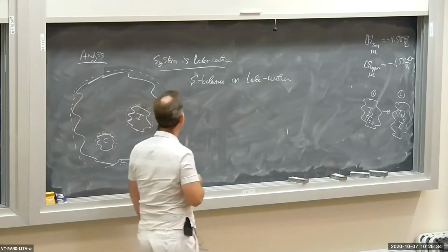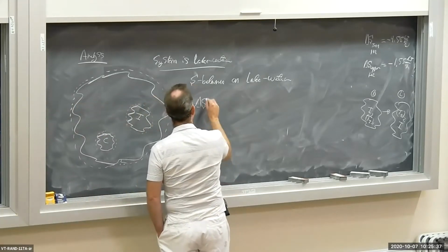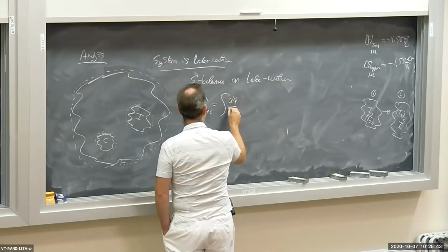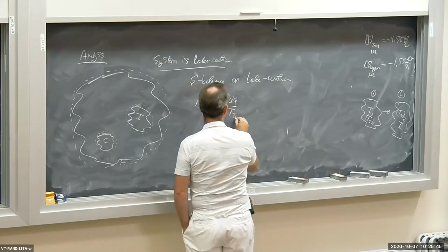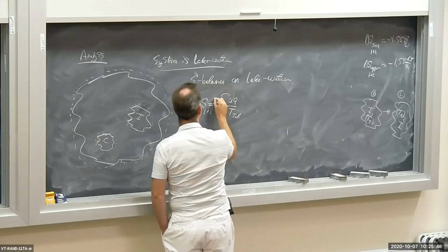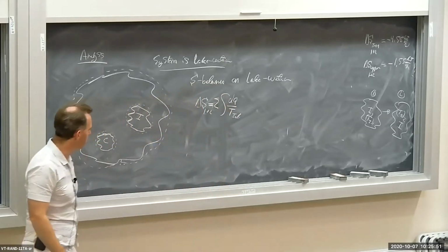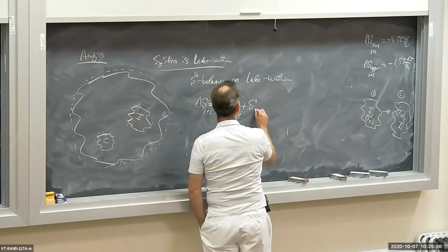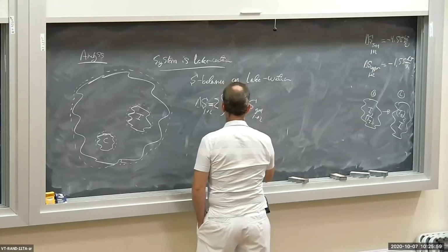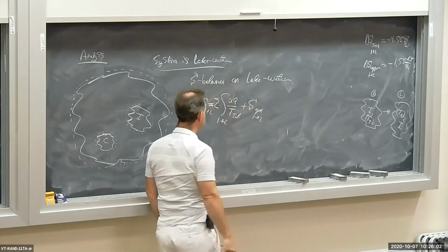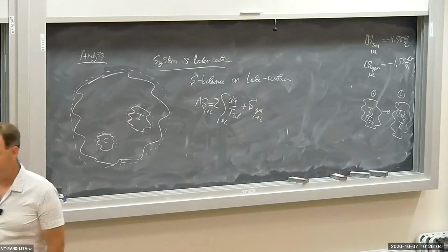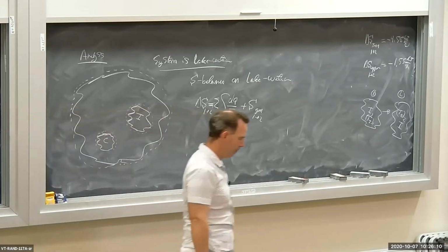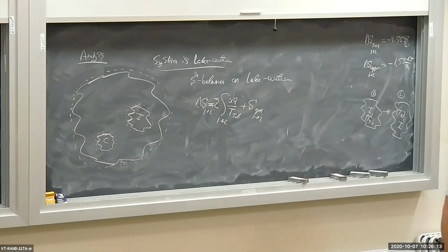So I have delta S from 1 to 2 equal to the sum of the integral of delta Q over T at the interaction. Remember, there may be multiple heat interactions going on, so we have a summation sign there, plus S gen 1 to 2. Now, this lake is very, very large. That means that the temperature of the lake isn't changing.